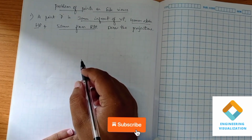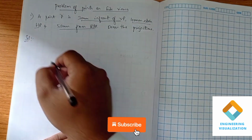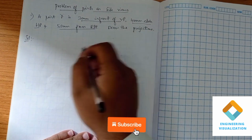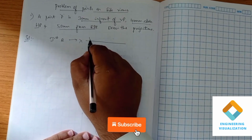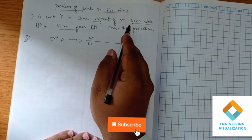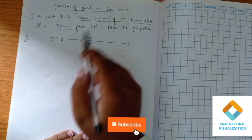In this problem, it involves three concepts. First, to identify the quadrant. In front of VP and above HP means it is our first quadrant. For the first quadrant, we know the notations: VP, HP, XY. That means first we are going to draw this first quadrant, top view and front view.